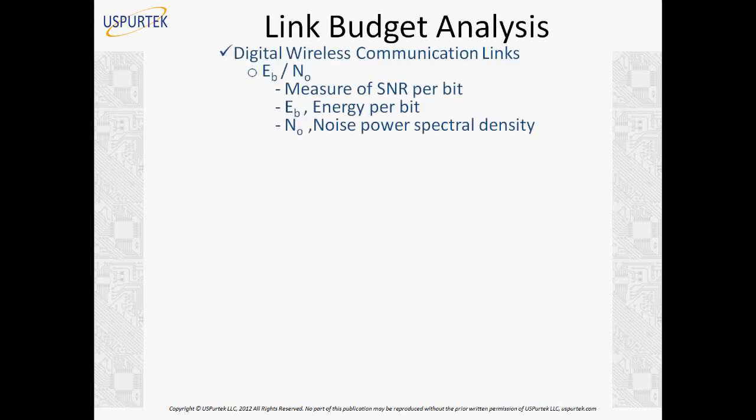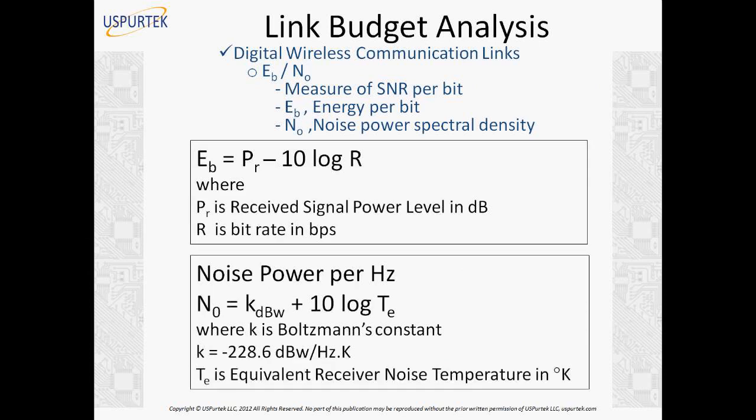So now let's go to a different type of application, a digital wireless communication link. Somebody had asked whether, when the signal level drops, it affects the bandwidth. Yes, of course it affects. If you are falling below your sensitivity level, your bandwidth degrades. And there is a term for that called BER, bit error rate. We always talk about bit error rate, BER, of a digital communication link.